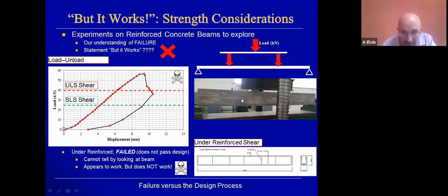My photo here, the rubbishy photo that some people claim has failed. It has not failed. It was taken right here at the unloaded state. The force deflection goes like so. Here's my serviceability limit state of shear, ultimate limit state of shear. The reason why I put danger is because shear cracks are much, much more dangerous than tensile or compressive rebar failures. So here we have it.